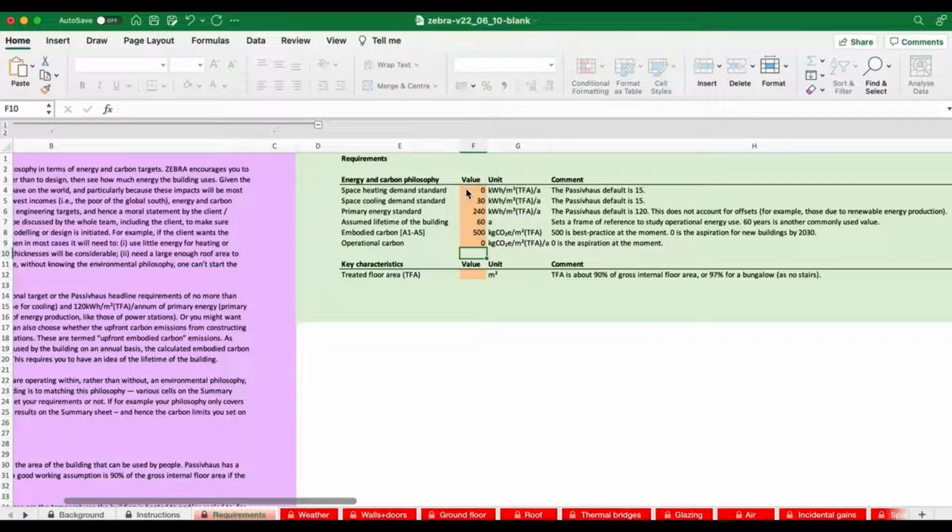So we're going to have some energy use from the various systems, but we hope to offset that completely by the PV on the roof. This will actually be a huge challenge for this building because it's a very tall building. It's got a lot of floor area compared with the roof area. It's much easier with a bungalow to put enough PV on it to run the bungalow. It's difficult on a 14-story apartment block.